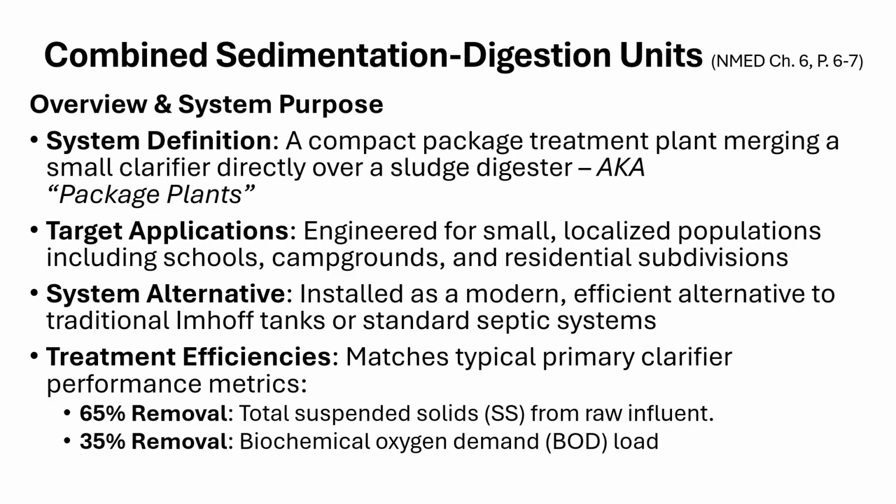With respect to BOD, they'll remove 35% of the BOD load from the influent to the effluent, the outflow. They'll take 35% of that BOD right away. They'll also process suspended sediments from raw influent, taking out 65% of those suspended sediments going through these package plants. So they are pretty efficient and they are pretty slick.